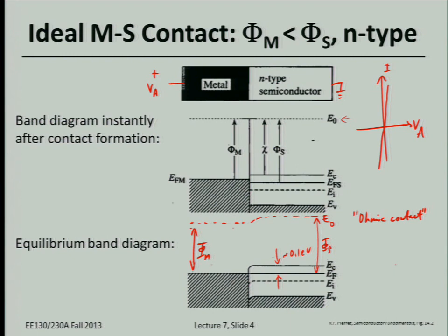Sorry, I thought the reason why the Schottky one wasn't able to go back. Okay, so that's a good question. In practice, the barrier to electrons flowing from the metal to the semiconductor is really small, within a tenth of an electron volt. So there's still plenty of electrons that have enough thermal energy to flow into the semiconductor. Once that barrier gets too large, then it might not be perfectly ohmic anymore. So you're saying the vacuum level changes.